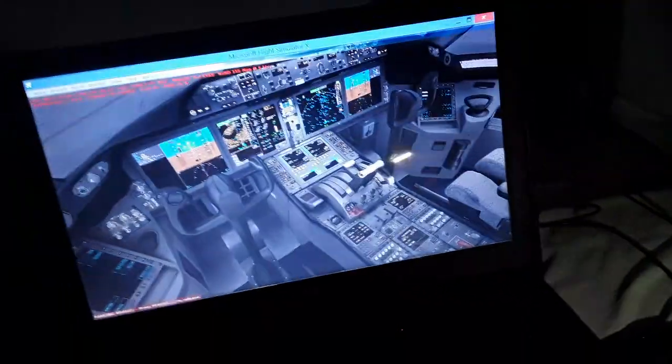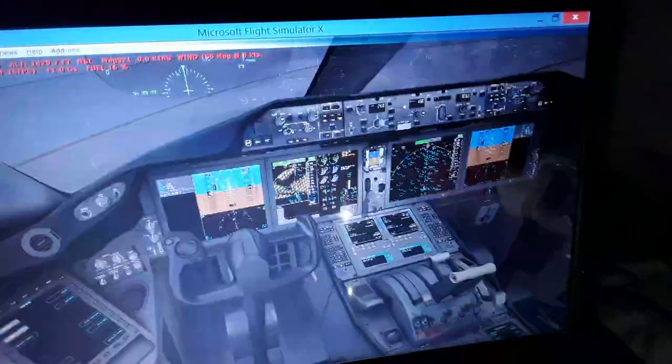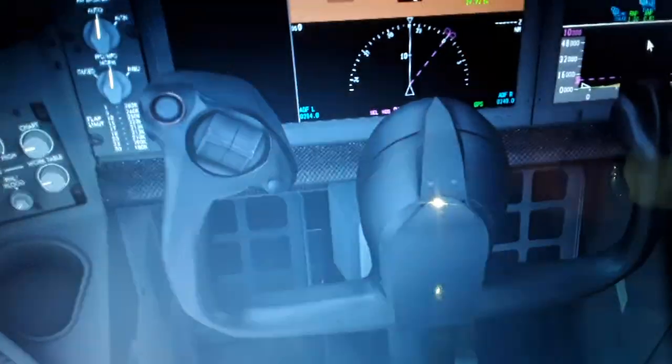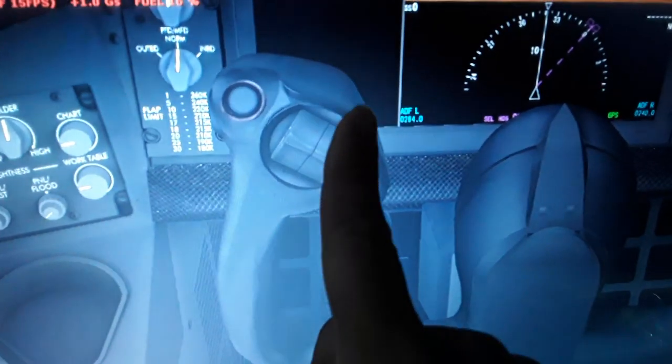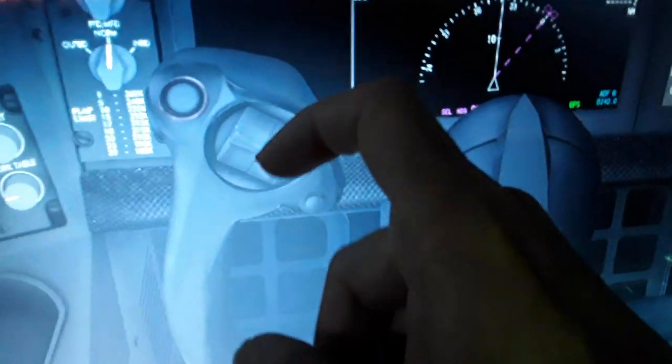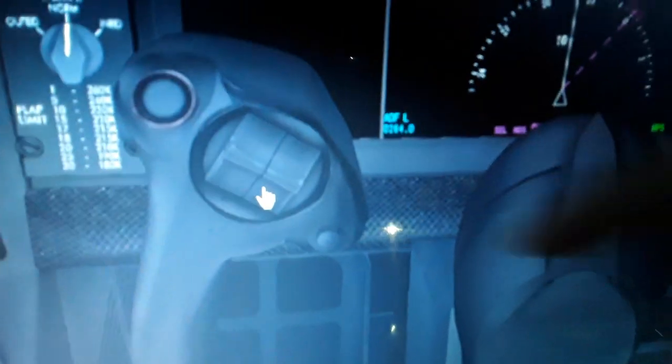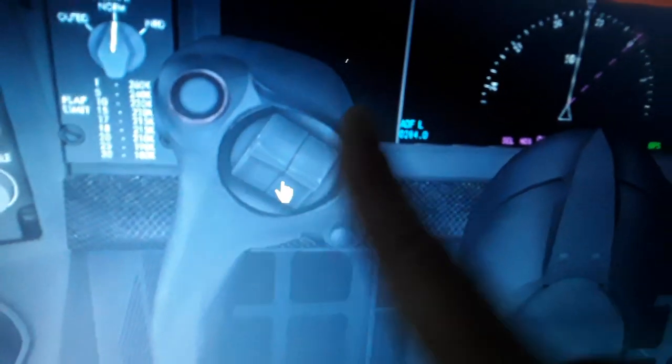We have also the horizontal trim stabilizer, the pitch trim of the horizontal tail of the elevator of the aircraft of the Boeing 787. So you can see we can use that. Also here you can, as you fly, you use this pitch trim switch here. This gives nose down of the aircraft pitch, and this gives nose up. So you pitch down, pitch up like this. This way is pitch up. This way is pitch down.